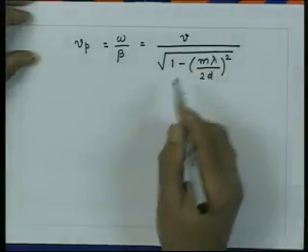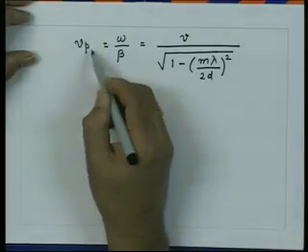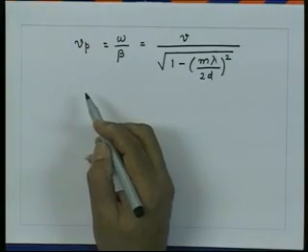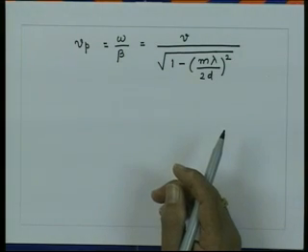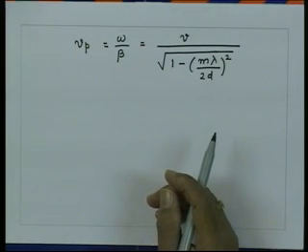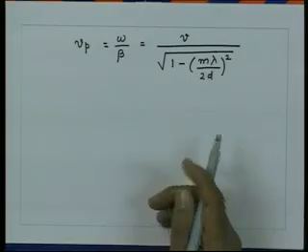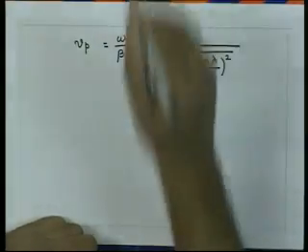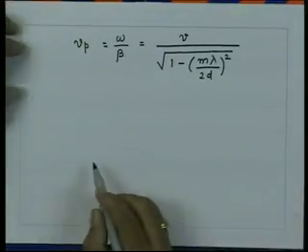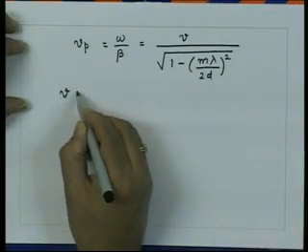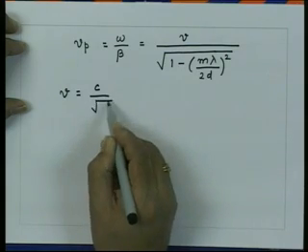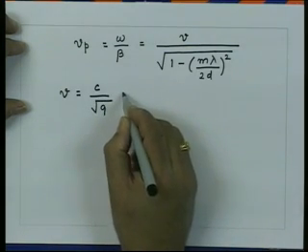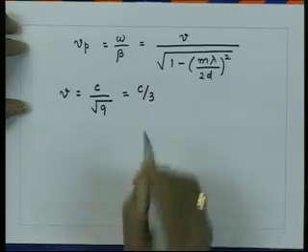We have the information of the phase velocity, which is 1.4 c. Now if I substitute these quantities into this relation, first of all the velocity v: since the dielectric constant of the material filling the waveguide is 9, this velocity v will be equal to the velocity of light c divided by square root of epsilon r, which is 9. So that is equal to c upon 3.